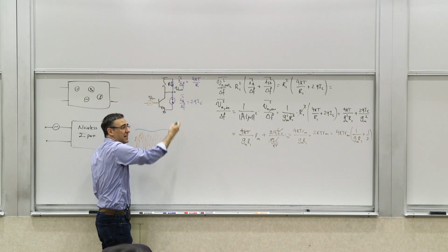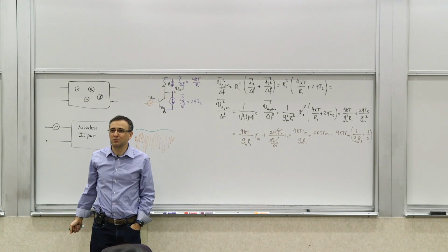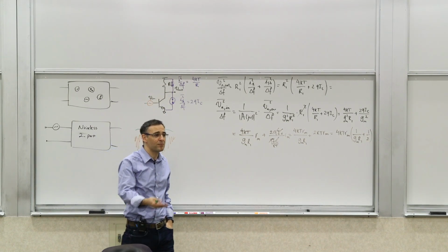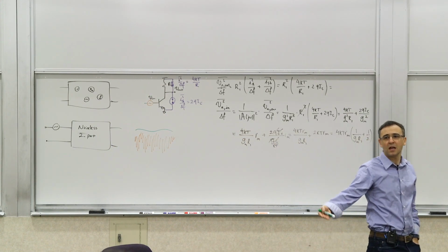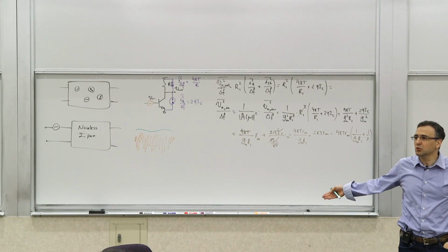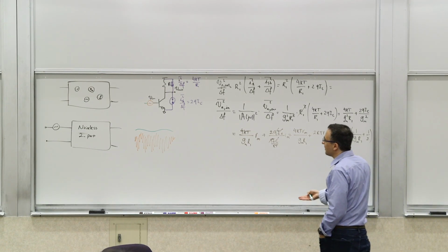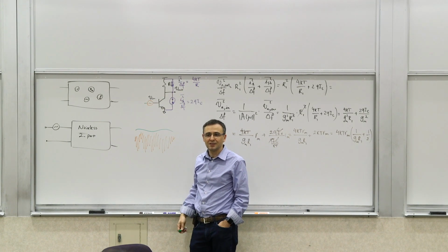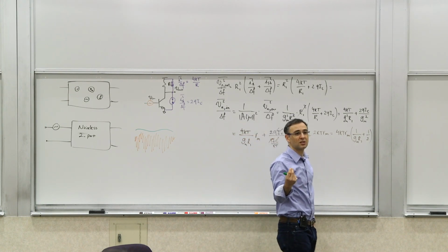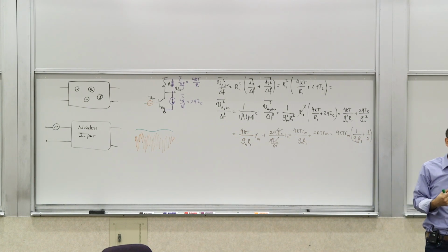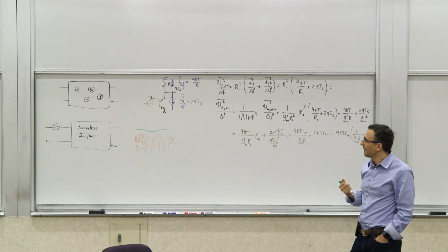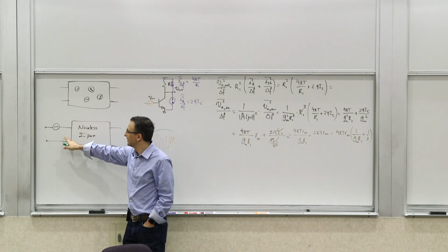No. I mean, this resistor doesn't care, for example, whether or not you put anything at the input. It will generate its own noise. So will the shot noise of the collector. It would be the same. If you're maintaining a DC bias current, it would produce the noise there. So the output noise is there. But somehow our model has broken down, because basically now this produces nothing. So this is an example to show you that this voltage noise is not sufficient to capture all the scenarios, right? Essentially, it only works when the source resistance is 0. So this model is incomplete.